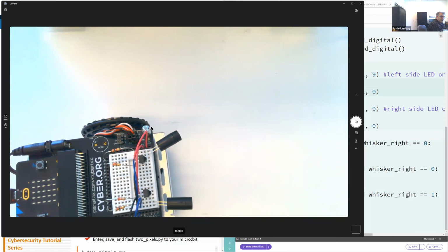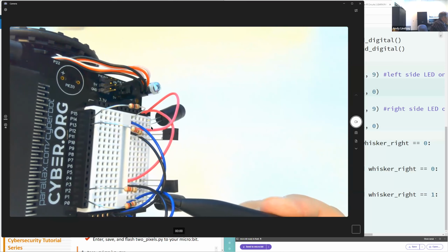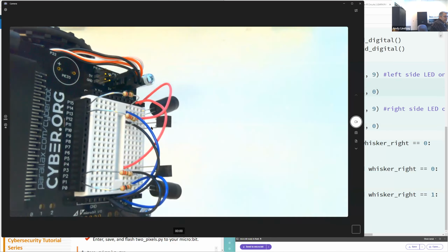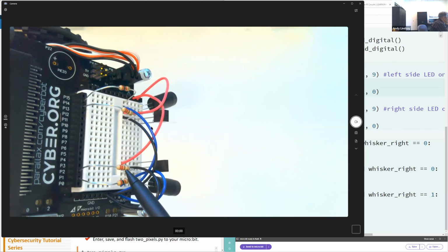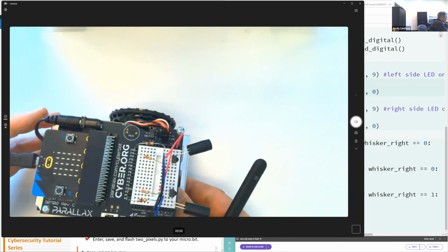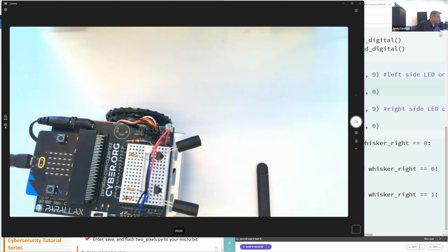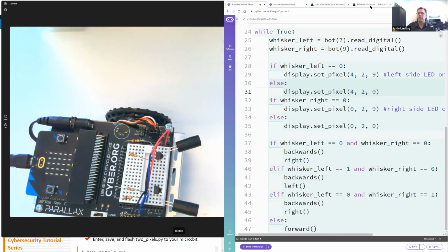Another thing to check is to make sure that on the infrared receiver, the topmost pin is red and going to 5 volts. The middle pin gets a black wire and is going to GND. And then the lowest pin is what's connected to the red-red-brown resistor. Let me see if I can get a better picture of that on the diagram.